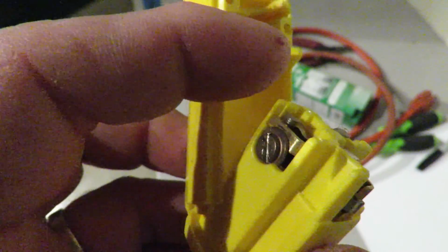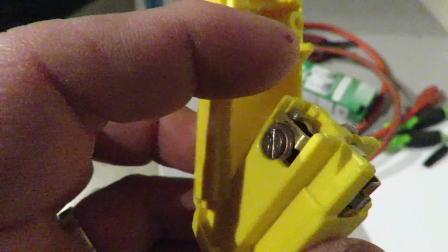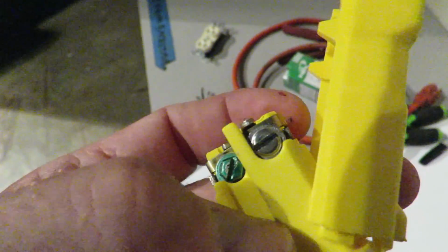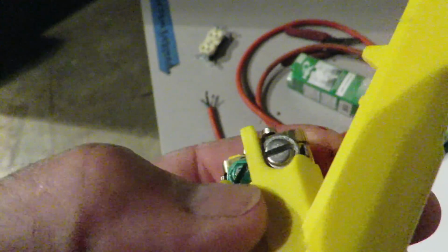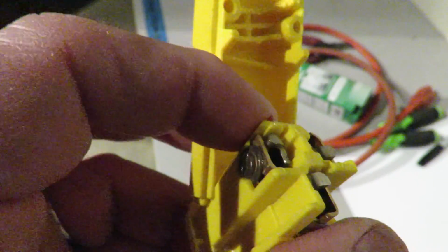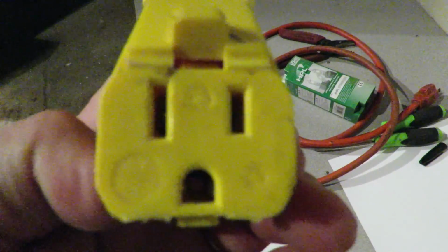So black, brass, black, brass, that's how you can remember that. Silver kind of is in the, I don't know, white diamond family. There's no way to remember that, but just remember black goes to the brass screw, and it is the smallest